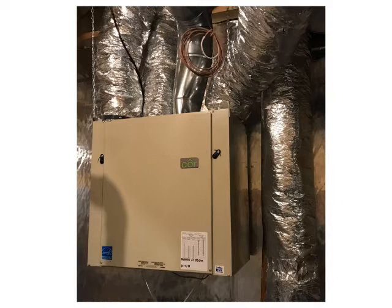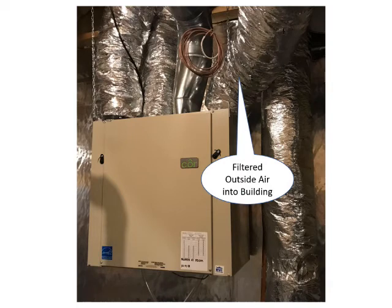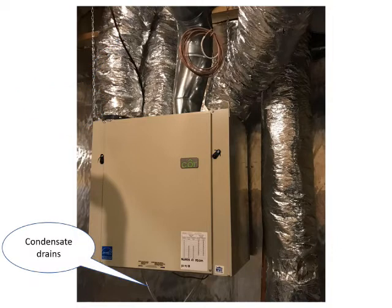So let's take a look at how these ducts work. We've got 4 ducts that come into this system. We have the air from the inside of the building. So this is sucking air from inside of the building. We have a duct then that is air that's now coming back into the building that's filtered from the outside. We have the outside air duct. So this is the duct that's bringing air into the HRV. And then the exhaust duct. So this is the duct that's actually taking the air to the outside. And we've got condensate drains for the little pans that are on the inside. So we'll take a look at that here in a second.